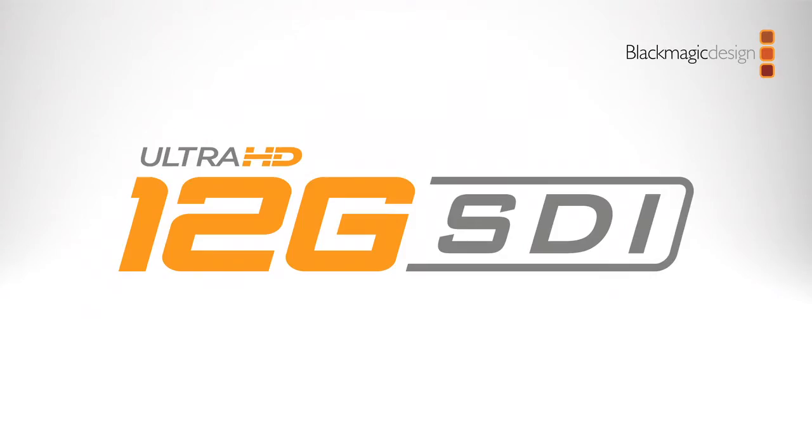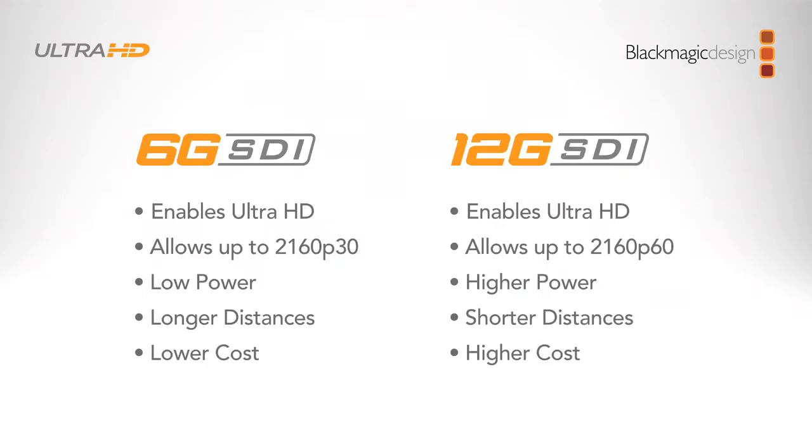And this is the first product we have with 12 gig SDI. I love 6 gig SDI, it makes Ultra HD possible. 12 gig SDI lets us go at a higher frame rate. So for us, the advantages with 6 gig SDI versus 12 is they both enable Ultra HD, but 12 gig SDI allows us to go up to 60p. But it is higher power and it's shorter distances and it's high cost. As you can see, the 6 gig products we've got are lower cost in some cases than the HD products they replace. So I think in the future, you'll probably see both coexist side by side. So the Onyx Express has 12 gig SDI built into it.